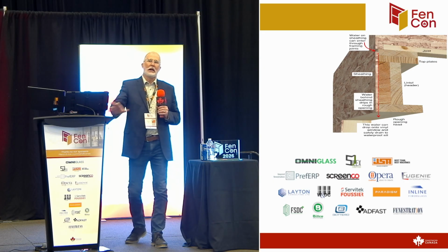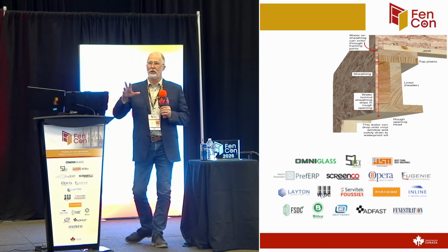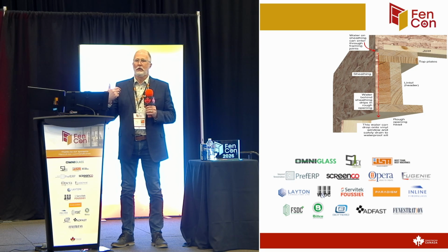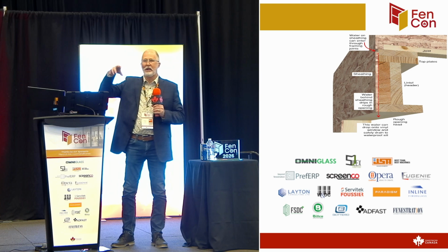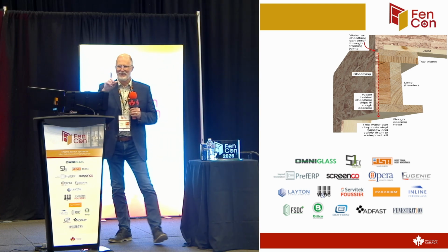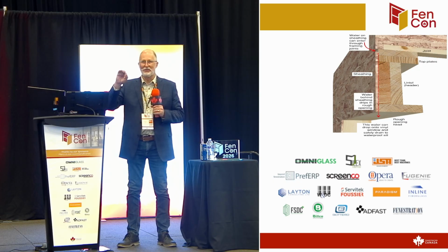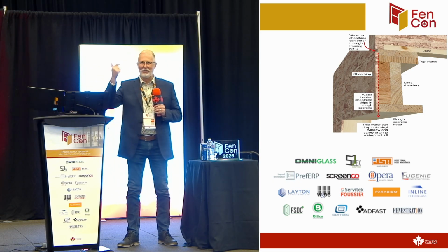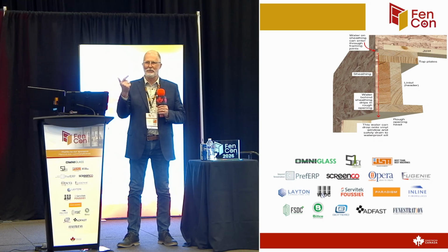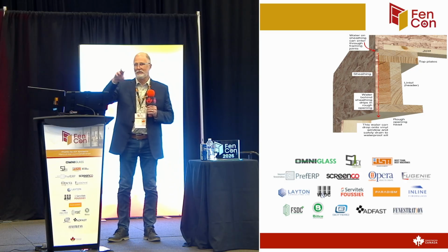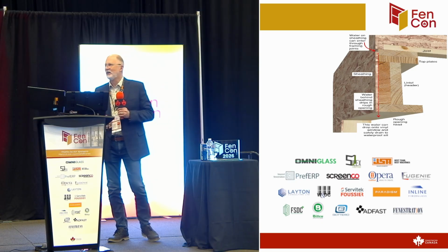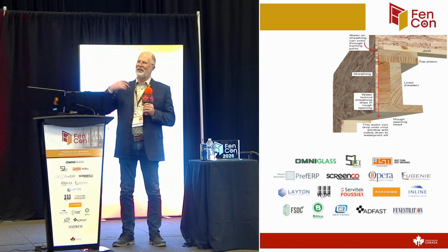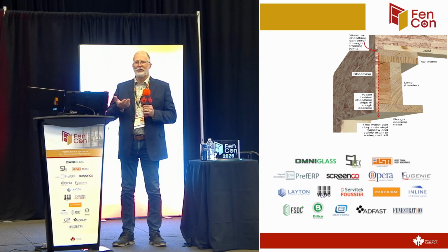You could ignore both of those and set up your mechanical systems to pressurize the building so that you never have air coming in. You could pressurize it so that it's pushing out, just like a commercial building, right? So you can take advantage. We're only talking about one dimension here, where we have basically 3 dimensions: the operation of the building, the performance, and how the mechanical system affects that performance. So the envelope is only one of the 3 things that I think about when I think about whether it's going to perform long term. But you're right, it's good to analyze both sides. That's why I would not leave the insulation out at the bottom. I would put something in that drains. Just risk management is all it is.